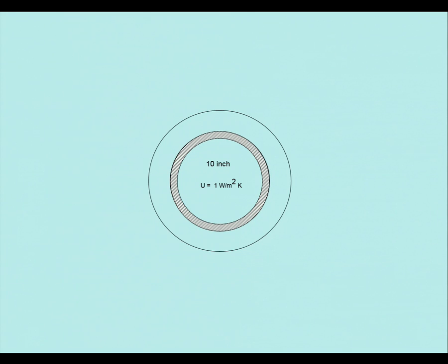If I go for a fairly high grade, a U value, K value of 0.07, that's the radial thickness I need, which is about 82 millimeters thick. Don't know where the colours have gone on this, which is 92 litres a metre.